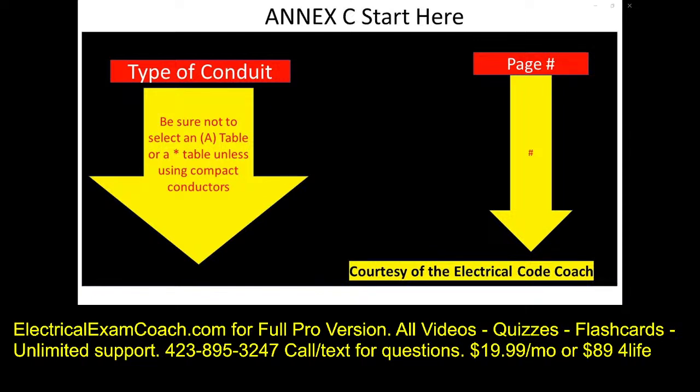There are several different types of conductors out in the industry. Some of them are concentric, but the ones that are compact are bound a little bit tighter, and you can actually fit more of those inside of a pipe legally. But for your normal pipe fill questions, they're not compact conductors. Matter of factly, unless it says the word compact conductors, you will never assume that they're compact conductors. And you do not want to use the A versions of these tables.